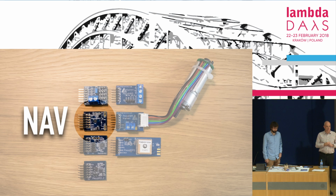It has 10 degrees of freedom: a 3-axis accelerometer, a 3-axis gyro, a 3-axis magnetometer, like a compass, and an air pressure sensor to have a height measurement. It's precise enough to know if you're a few meters up. And a temperature sensor for good measure in addition. So it's actually 11 degrees of freedom in one Pmod.